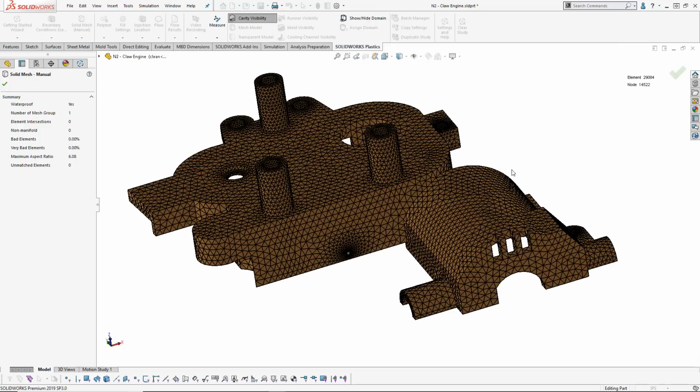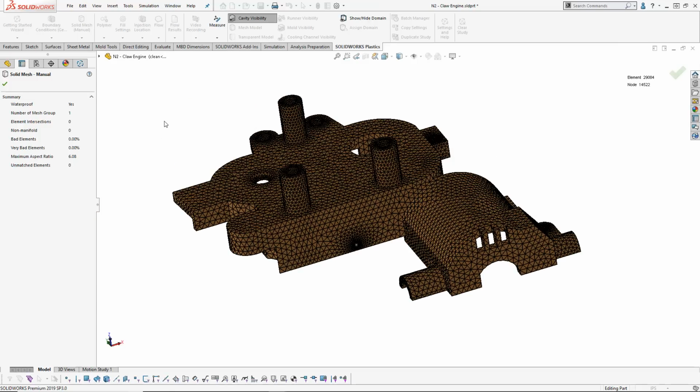So those types of errors would show up, and that's also another way to check your modeling. I've seen several of them where when I did the automatic mesh, it had a really refined spot in one area. It was this really thin spot in the part, and it showed up during the meshing process that you couldn't even see in the model until I did that.